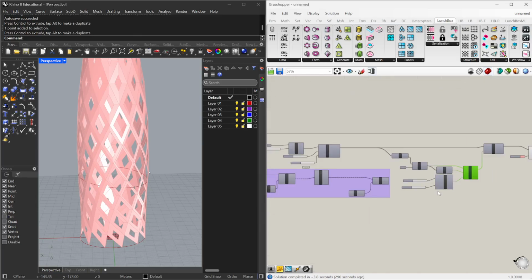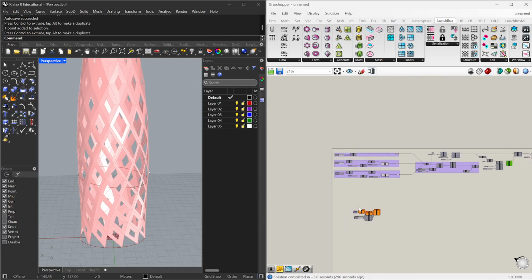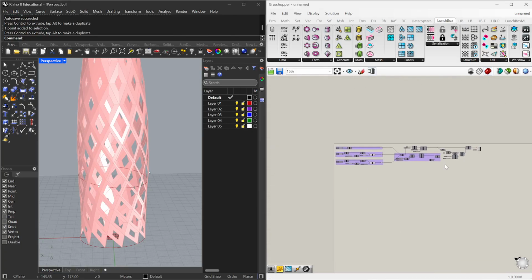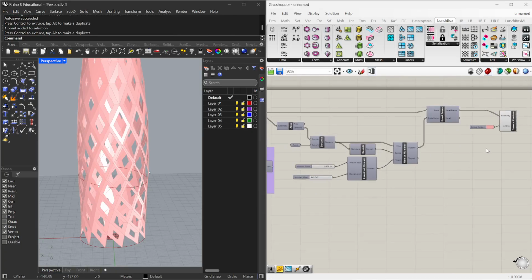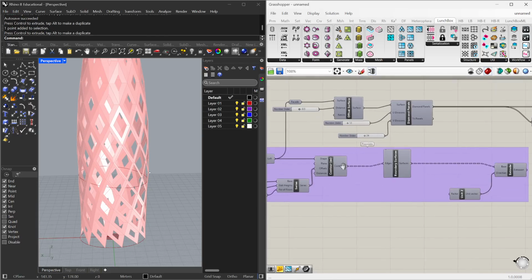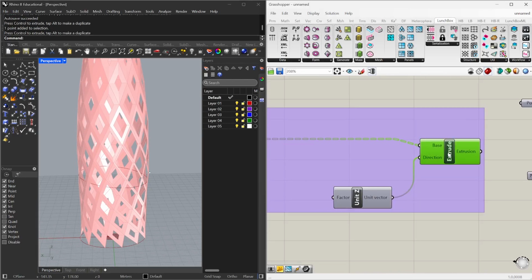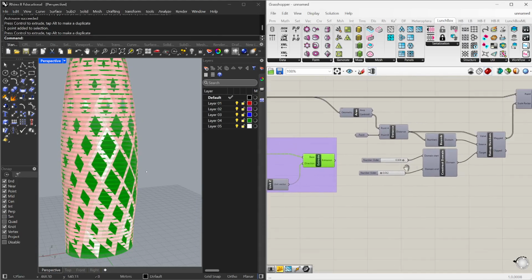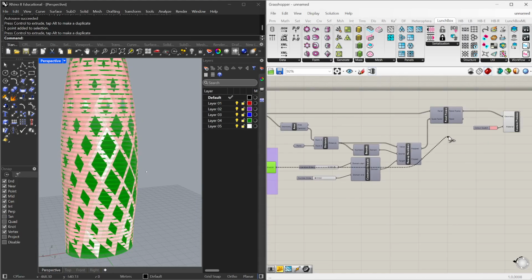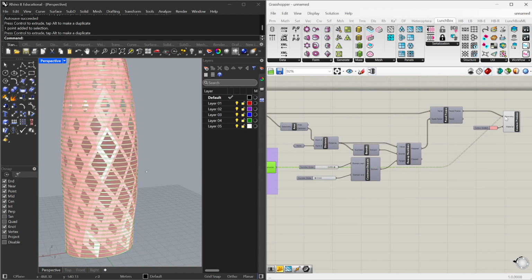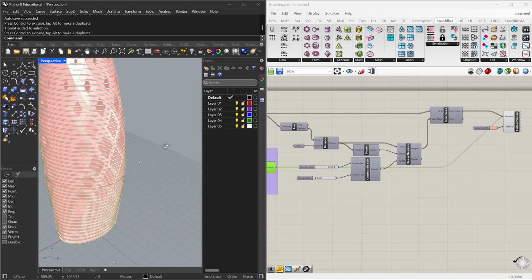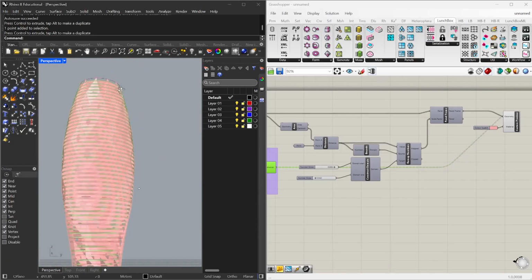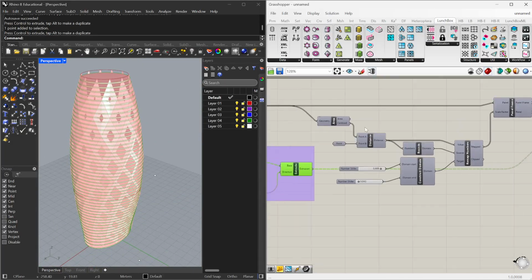So you just built your first parametric design script. So now we've created the logic. If we wanted to put our floor slabs back in, our extruded floor slabs, we can do. And we can see those. And I could even put them into the preview as well. If I hold shift whilst I'm putting that in there, you'll see that our panels, our floor slabs are there.